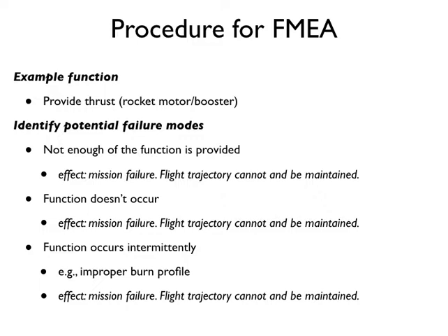Especially in case where you have, let's say, a new portion of the design. So if you're designing a new weapon system and part of the system is reused, but part of it is fundamentally new design, and you want to focus your FMEA a little bit more on that new part of design because it's more uncertain, you may find some failure modes for the components there, but you may also use an approach like this to develop more failure modes.